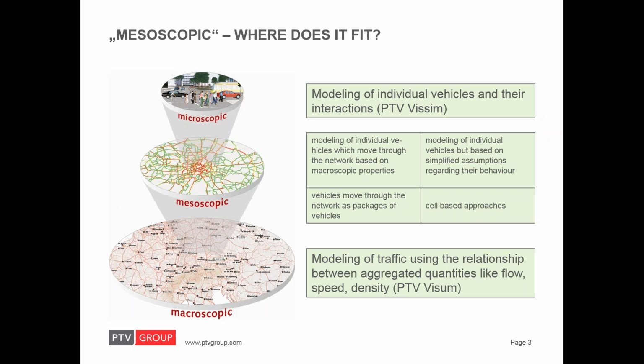And also cell-based approaches have been used. In these models, the road network is divided into cells, and depending on how many vehicles fit in such a cell, the approaches are subdivided in microscopic and mesoscopic models. So we see that the mesoscopic level is less well defined, but it clearly differs from the microscopic and macroscopic definitions. We will see that when we come to the description of the algorithms.